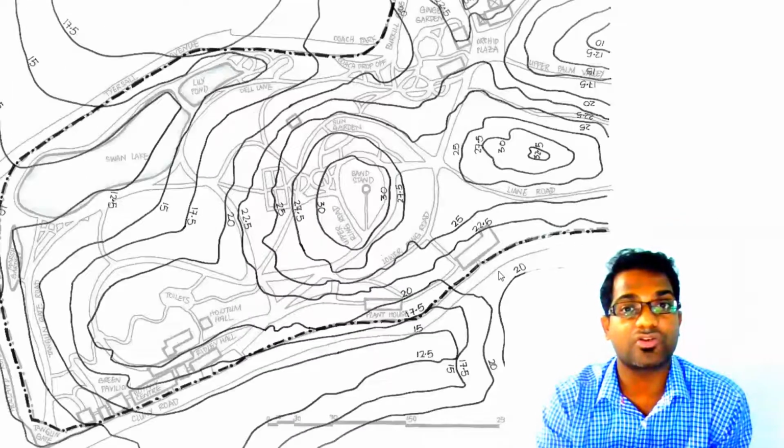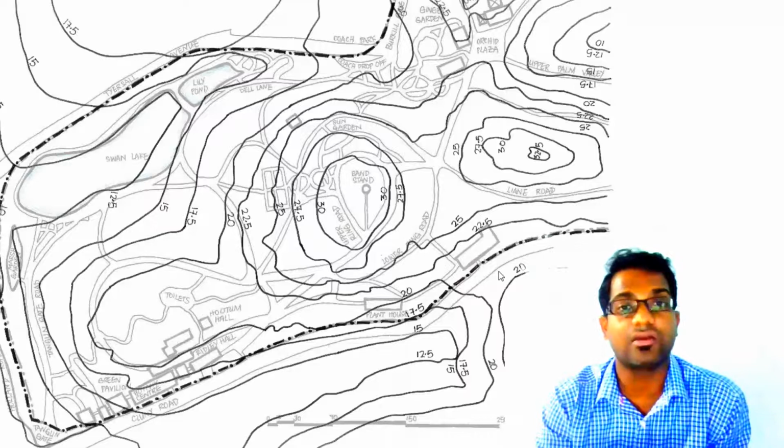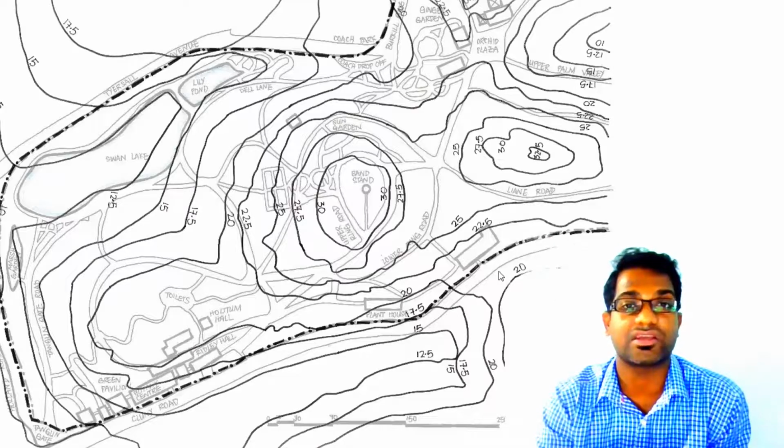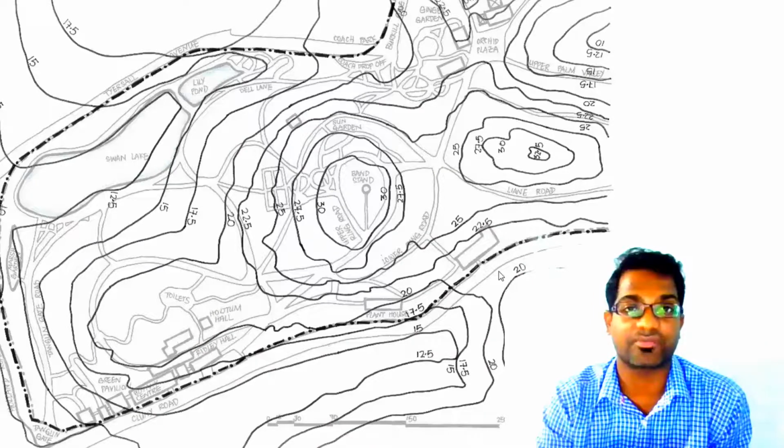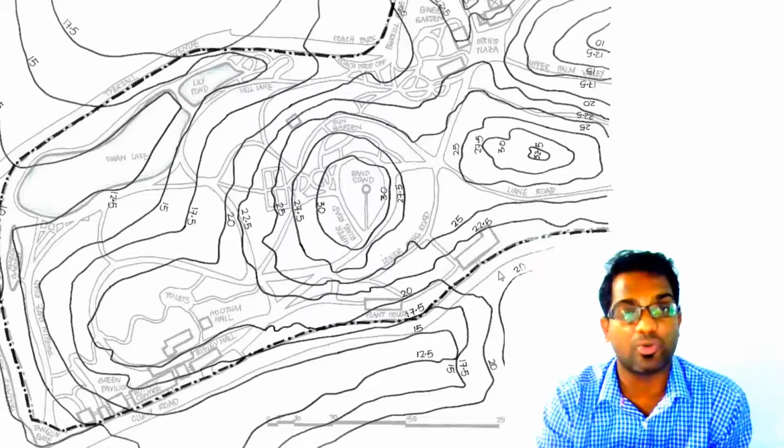These lines are also very important in order to design a water supply or a sewage layout for any city or town. Often, sewage water and water supply are carried to the households due to gravity. Gravity means it flows under its own weight. There is no need of a pump at all. If my reservoir is at a higher elevation, and I connect it with a pipeline to the lower elevation, if I open my valve, then water or sewage will automatically travel due to gravity.